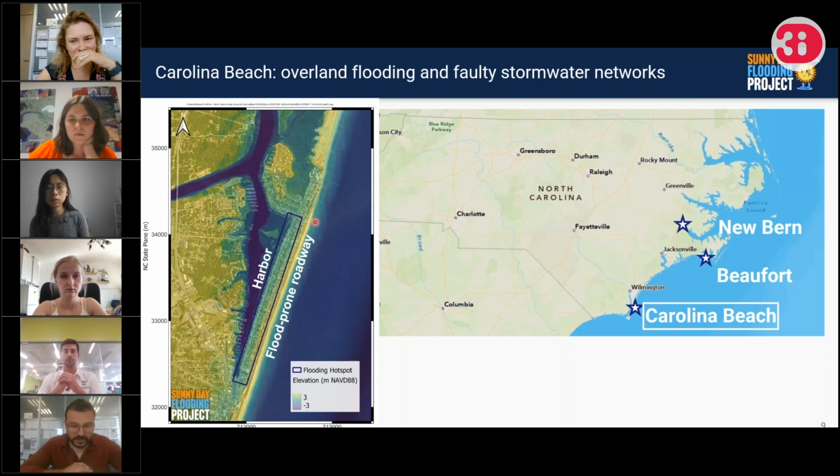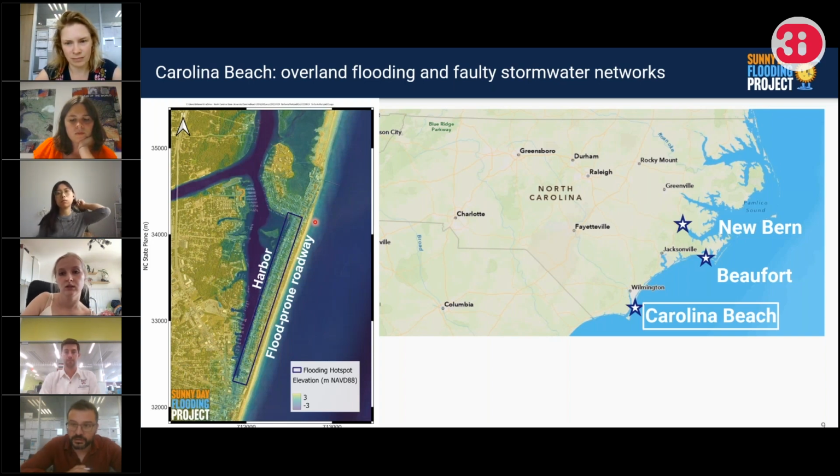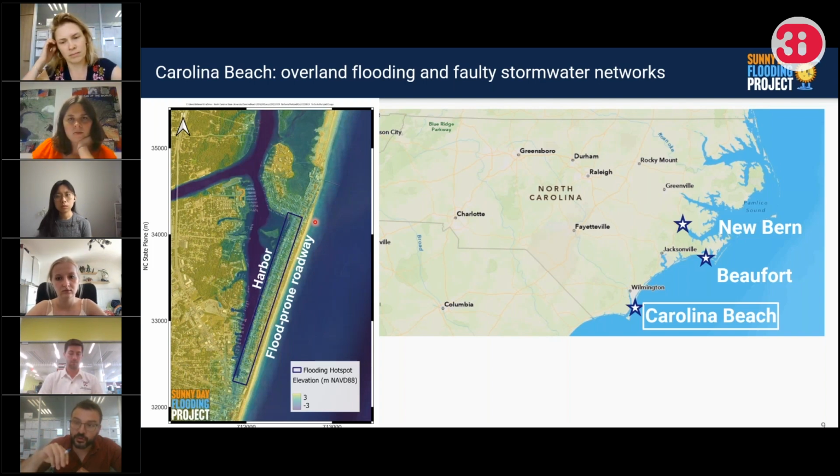Okay, very nice. I have actually a second question. More than a question, it's an observation, because I found it very innovative. You are using these cameras to detect the floods, and also the pressure sensors to measure the water levels. I wanted to ask if you know about this open source Python package called Open River Cam, because once you have the cameras, you can install these Python packages. And basically, if you have a camera, you can also calibrate it to measure flow velocities, which is another parameter you can use to validate your model.